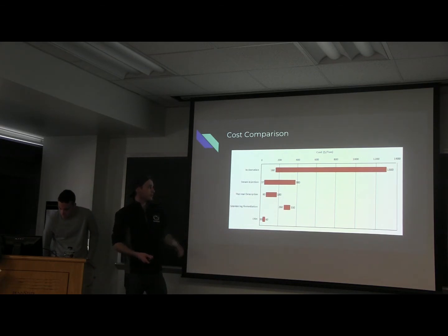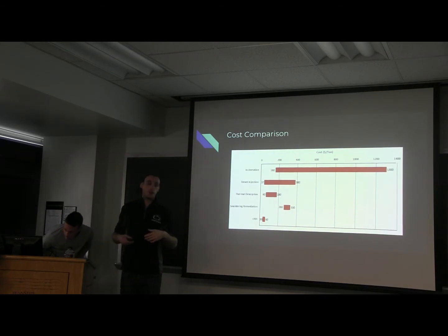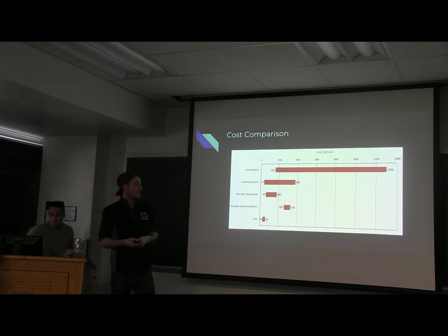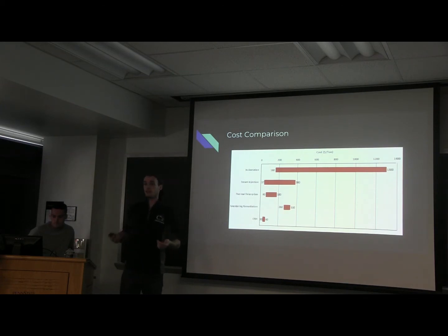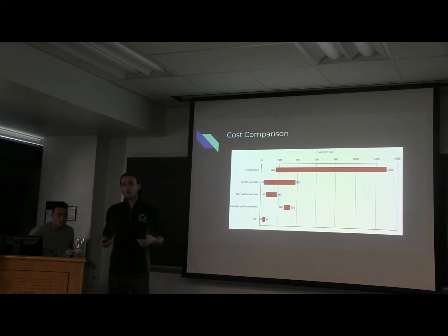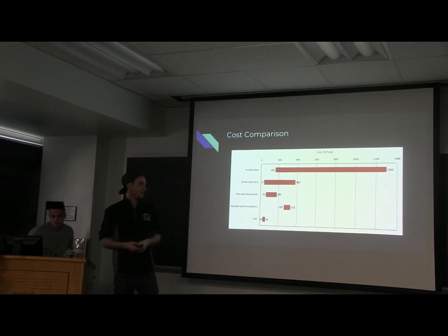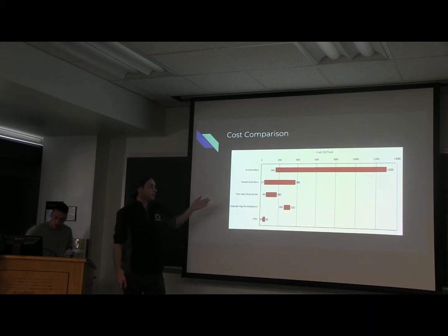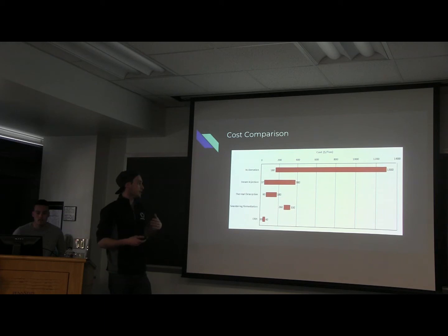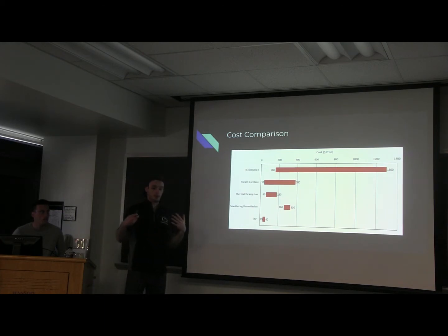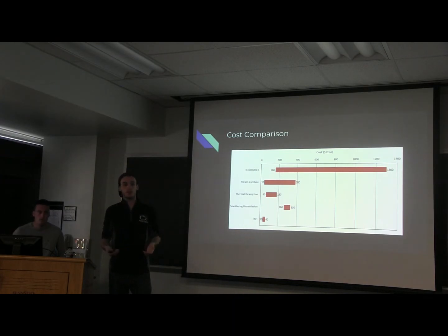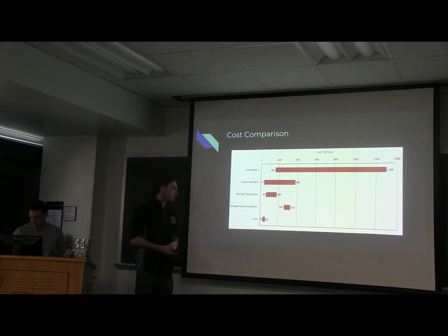The next most expensive method is going to be steam injection. That again varies quite widely. Again, it's going to be based on the limitations of the actual site. And you're doing it in situ in that case, so again, your prices are going to be increased for that reason. Next, we have thermal desorption. It's between $60 and $180 per ton. Again, the range is getting smaller as we go down, but all of these prices are going to be basically limited by the applicability and the types of soil and contaminants that are going to be at the site.